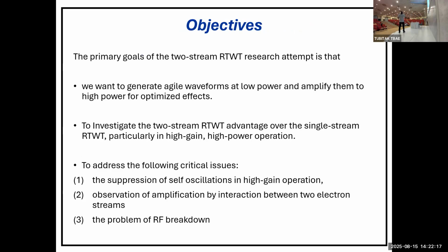the idea comes, I think I mentioned this, from the low voltage helix traveling wave tube. When you have multiple beams with different velocities, you could increase the bandwidth and increase the gain of the amplifier. That was done at lower power, lower voltages, and for a lower voltage helix, you can actually control how to drive these cathodes. Basically, you can have two power supplies and drive them.